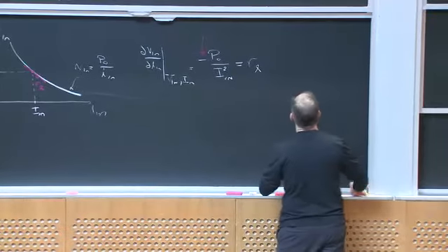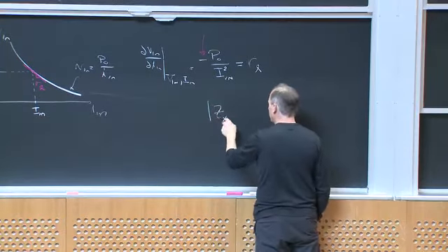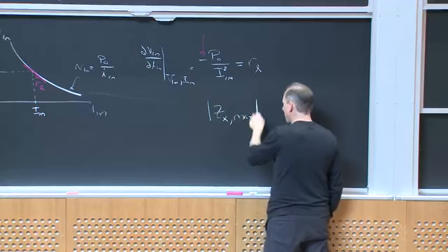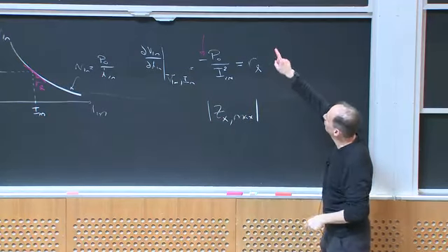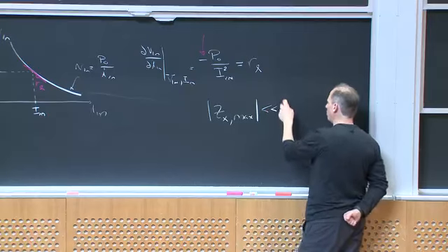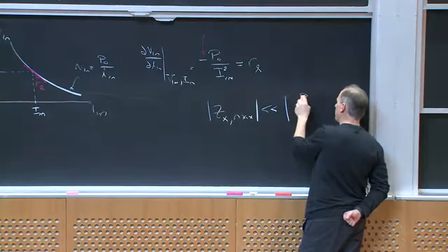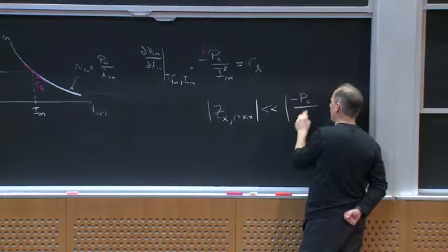Okay? And here I've shown you the simplest case for RD, but the more general statement of this is that we need the maximum output impedance of my filter across all frequencies to be well below the magnitude of P out over V in squared.